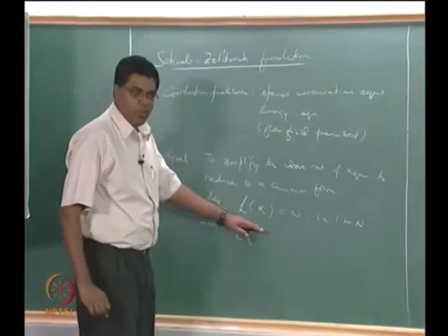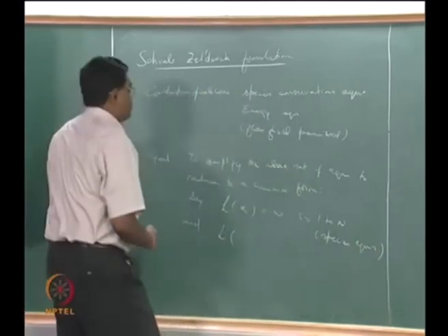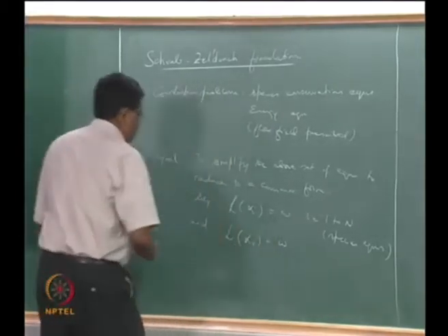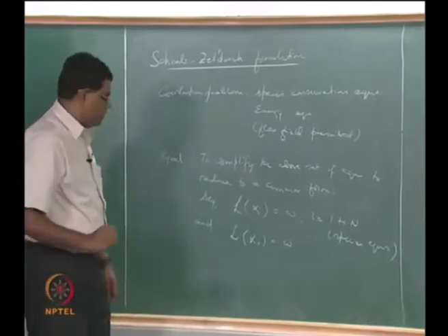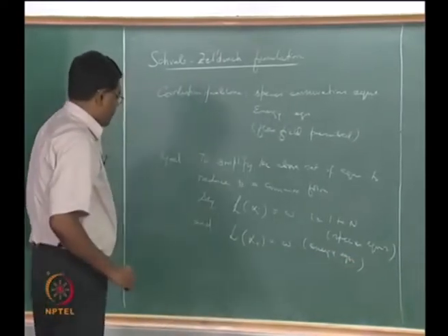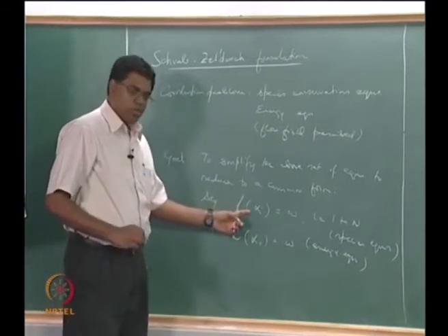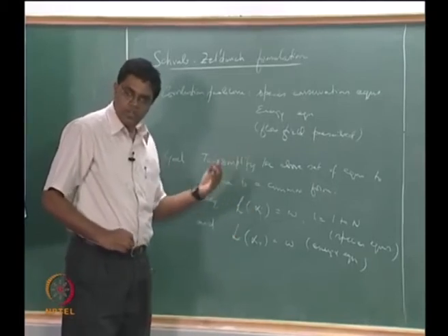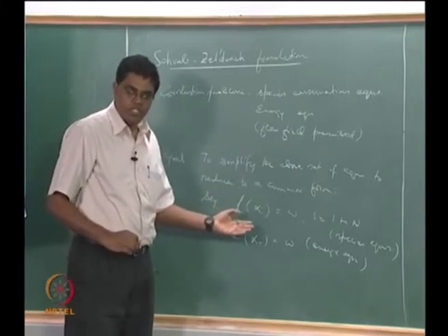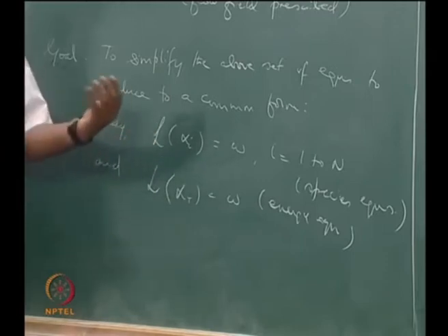So obviously those are the species equations, right. Then let us suppose that we can now form an alpha_t which is also equal to omega, okay, and this is the energy equation, right, and that's one equation. What we expect is alpha_i should be related to Y_i in some way, okay, the primary unknown corresponding to the species equations, Y_i being the mass fraction of species i, and alpha_t should be related to temperature in some sense, okay, in a fairly direct way.